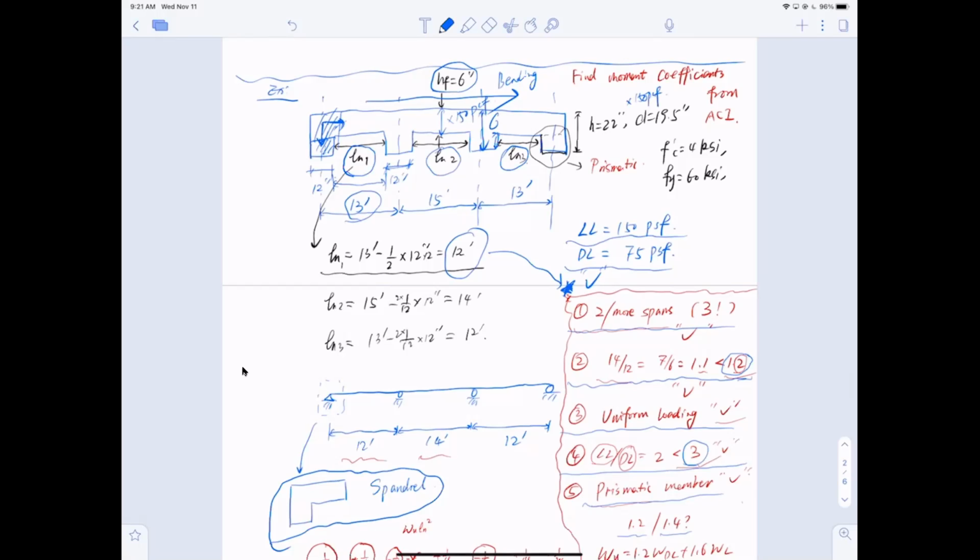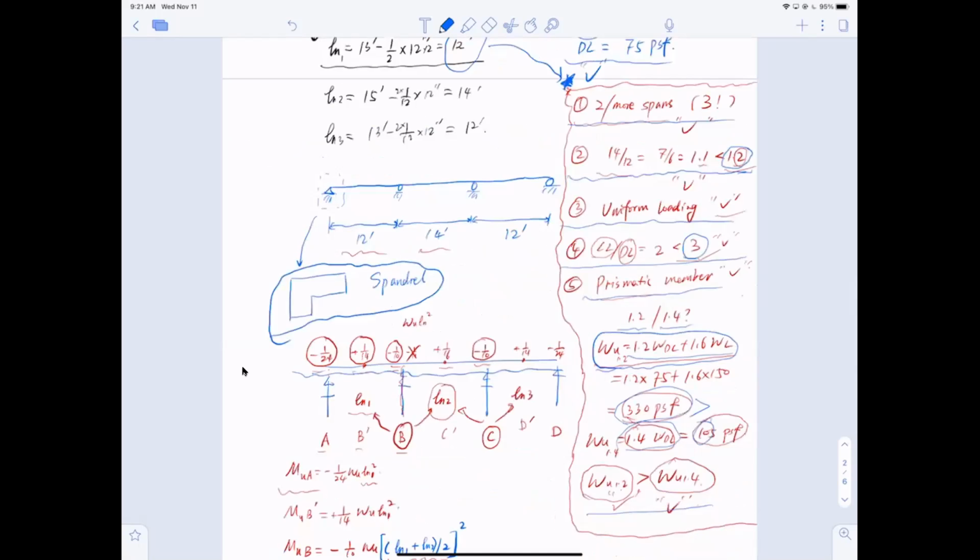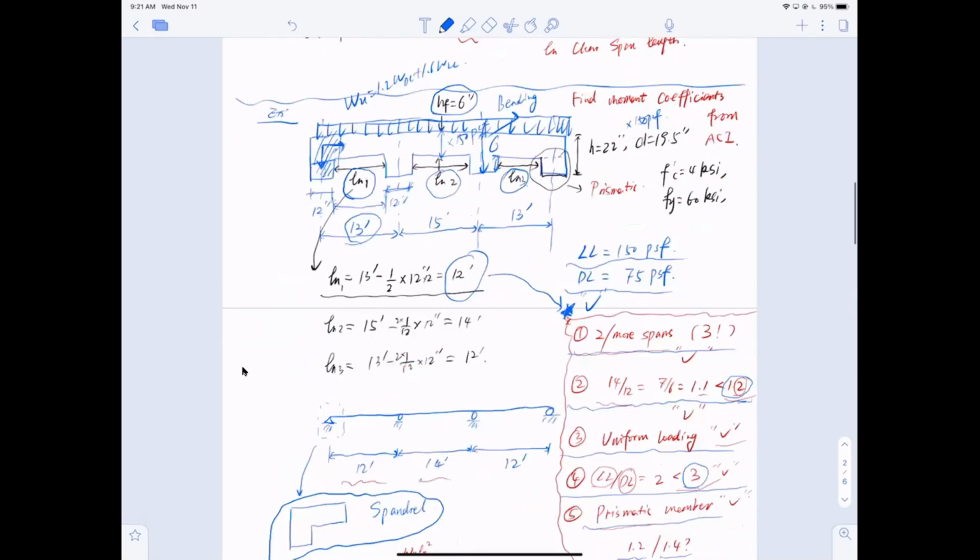Now, pay attention, folks, when we say the live load and dead load, these are distributed like this, along this direction, okay? So you have to find omega u. So omega u is simply equal to 1.2 dead plus 1.6 live, okay? And when you run the checks on the right-hand side, you know whether this dominates or not. If this does not dominate, I mean, if the 1.4 dominates, then stop doing it. You have a problem, right? So make sure you can use that.